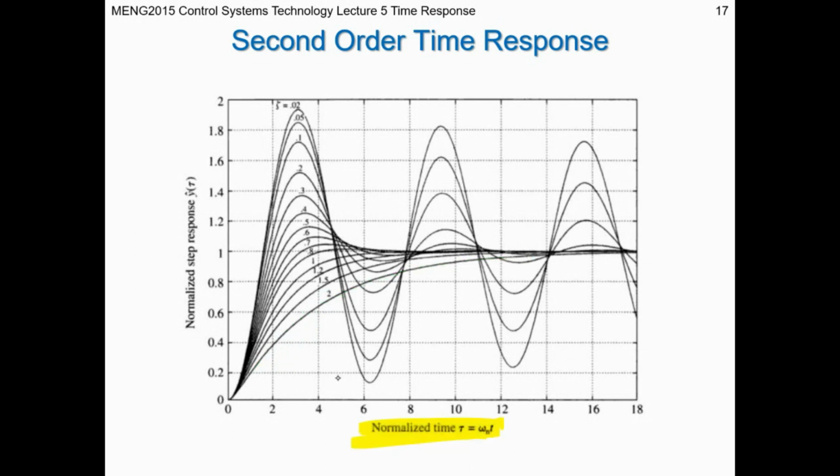And this is, in fact, normalized time. So we have taken time, tau, equals omega n times t. It's factoring out the effect of natural frequency omega n from the system by normalizing it. That's why all of these correspond. So it doesn't matter what type of system you have. If you want to use this chart, which is actually provided in the exam paper, say you find that the damping ratio zeta of a system is 0.2, and I ask you what's the time to peak overshoot?